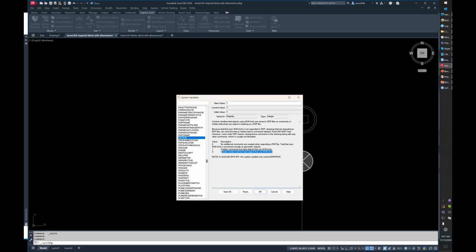A building is drawn in Revit, then it is saved to AutoCAD. It's actually exported, but yes. While graphically each door is a 36-inch door, each variation in Revit brings in a separate block. Is there an easy way to change that? With the export settings in Revit, no, there is not an easy way to change that. Going from Revit back to AutoCAD has always been painful. There are some things we can do, but for the most part, it's always going to be a different door with a different block name. Has there been any new options added for dynamic blocks? No. That's an easy one.